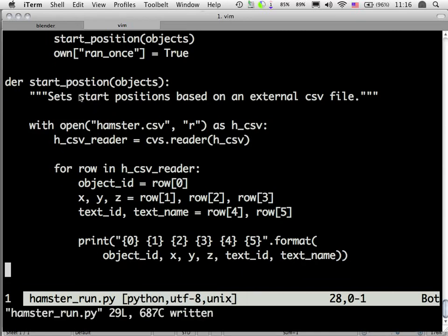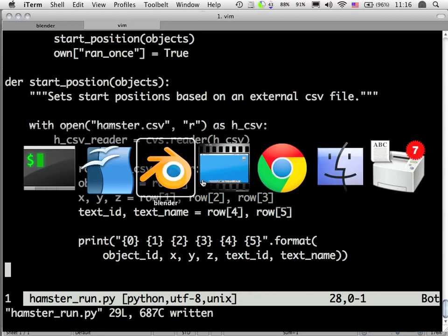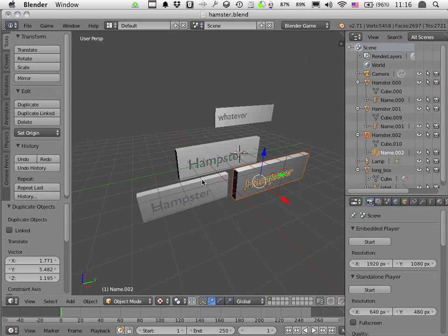All right, I go back to Blender. I'm in Blender. I go to game, but I remember one of the things that's good to do is to add something called empty, because when you're trying to set up your camera, it's good to have an empty object for your camera to focus on.